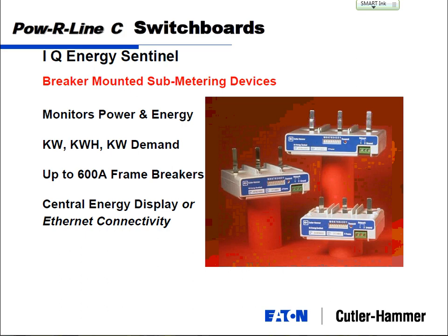Do they talk to each other, or do you have to read them individually? These ones, yeah, there's not even a display on them. So this is an option where you would daisy chain your 12 of them together in a switchboard. Then at the front of the switchboard, you could put one display where you can toggle through and scroll through your different ones if you wanted to, manually reading how much energy is used. Or you could put an Ethernet card in there and take it somewhere, so the building manager can sit at his desk, pull up the same information, and maybe even be able to generate some.